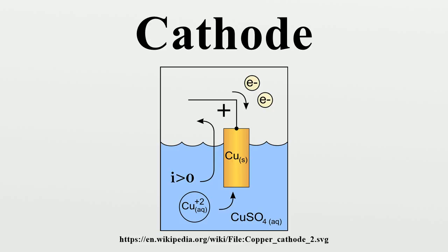The depletion layer at the junction is at the origin of the diode's rectifying properties. This is due to the resulting internal field and corresponding potential barrier which inhibit current flow in reverse applied bias, which increases the internal depletion layer field. Conversely, they allow it in forward applied bias, where the applied bias reduces the built-in potential barrier.